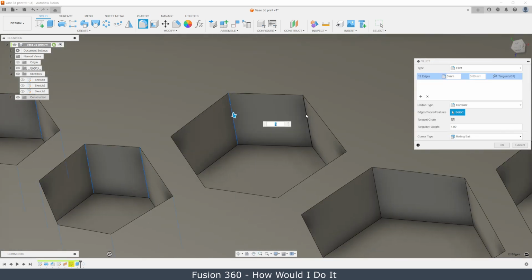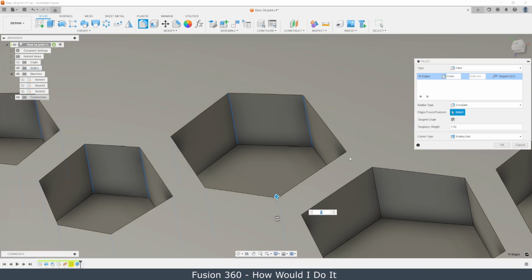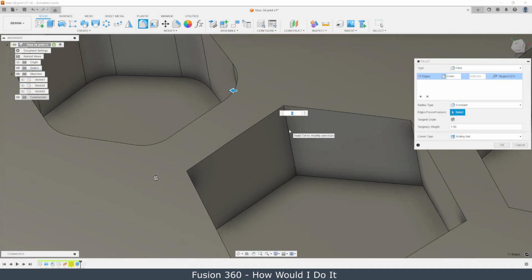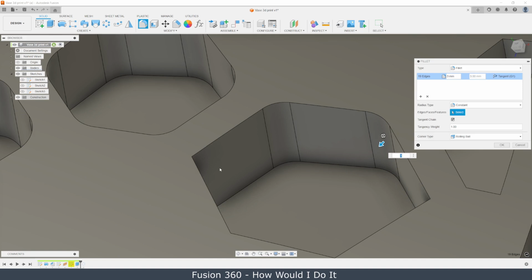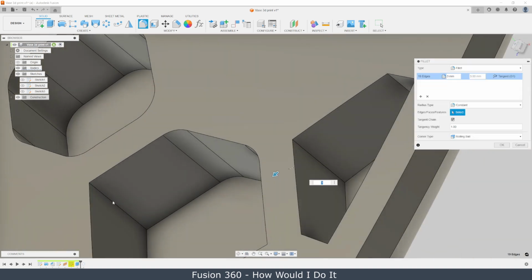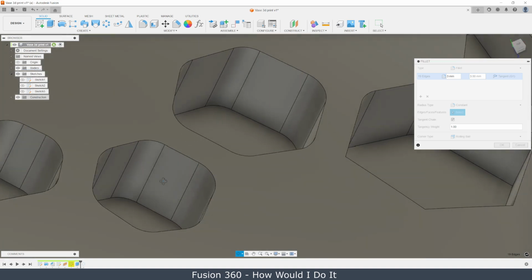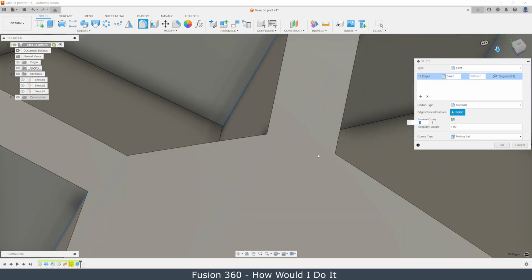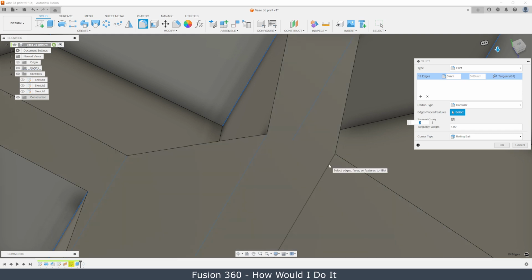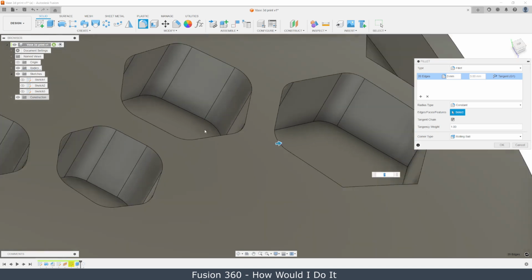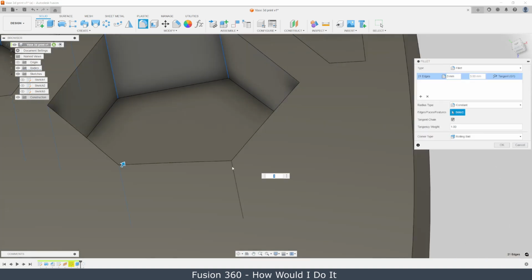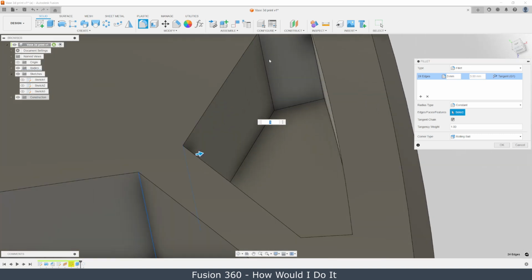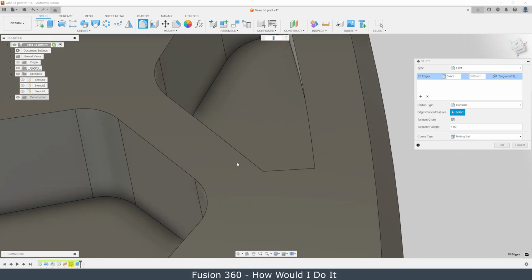So when selecting edges you don't have to go like here to have it visible, and here you have visible edges. So now we don't have to go here to select this edge, but we can, even if it's not visible, we just press Ctrl and go near that edge and it will be shown and we can click. Just press Ctrl and go for the rest of these edges. Hold Ctrl for all of these.